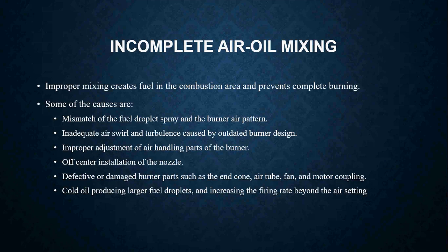Some of the causes that are going to make this occur are a mismatch of your fuel droplet spray and the burner air pattern. Inadequate air swirl or turbulence caused by outdated burner design.